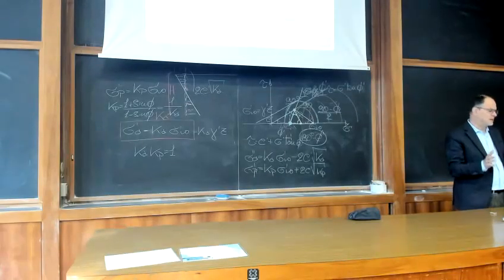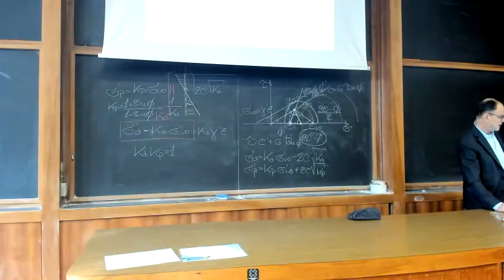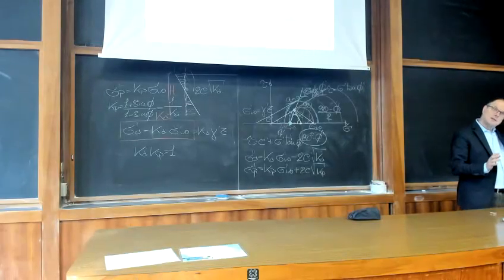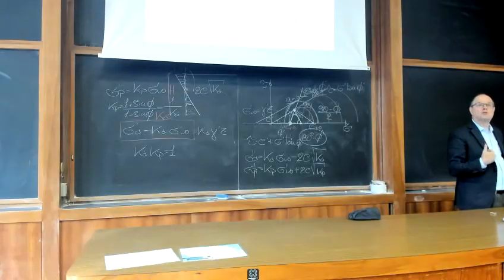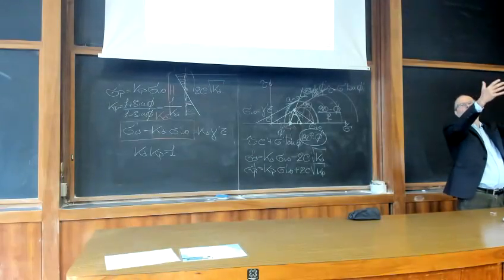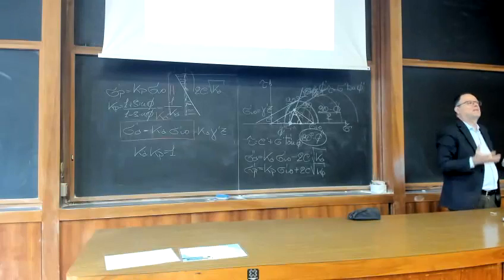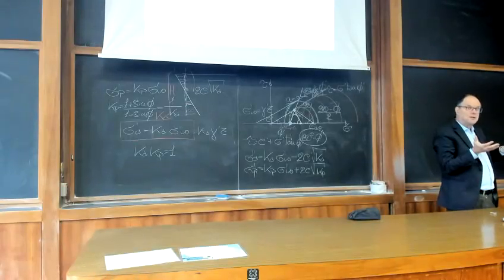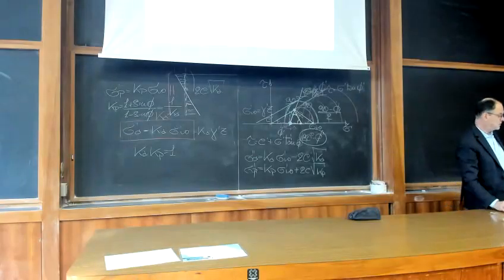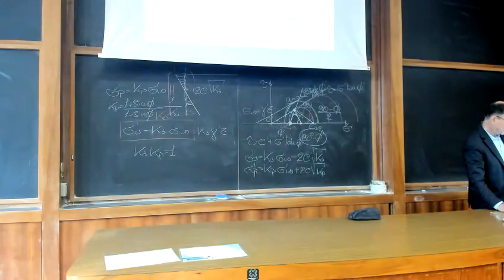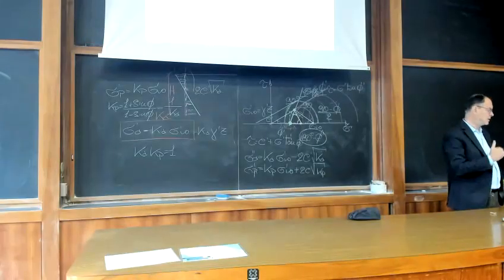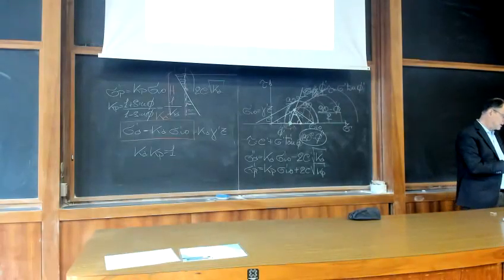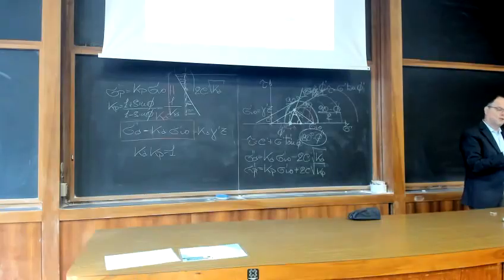Now the only thing is that the stresses acting on the footing come from the soil. The load comes from the superstructure, but then there is the reaction, the contact pressure of the soil. And so you have to design this structural element once you have determined the contact pressure of the soil.